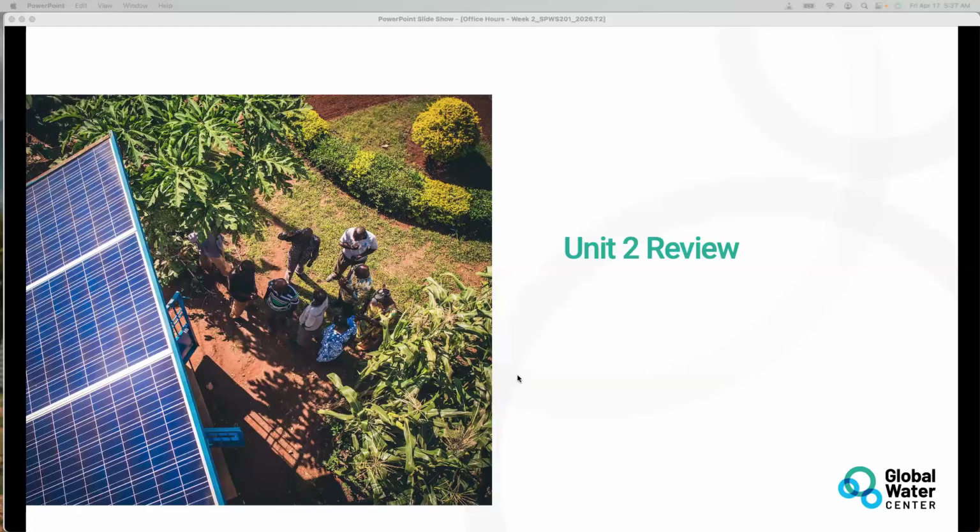Yeah, maybe on the casing part, what you mentioned is we usually use blind casing at the bottom for the stability of the well. And then the screen one will be based on the logging of that well, where we assume that we can get enough water. We put screen casing, and where we might face clay soil type that will disturb the water turbidity, we put blind one.